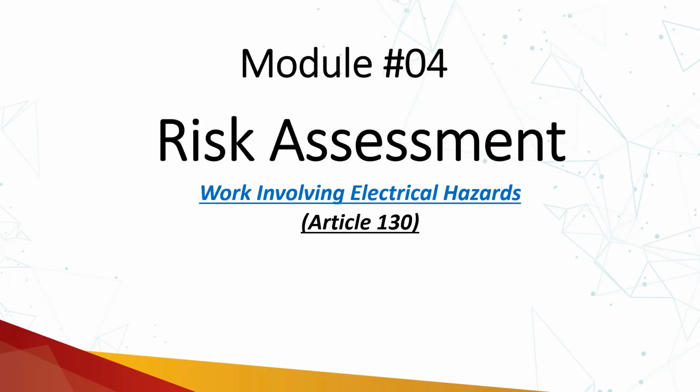But after establishing an electrically safe work condition at that particular location, you are performing some electrical task like diagnostics, or you are using some electrical hand tools or other things. Then a separate risk assessment will be performed to look into how the task will be performed in that particular case, and what PPE is required. But the initial personal protective equipment which was required for establishing an electrically safe work condition will not be required